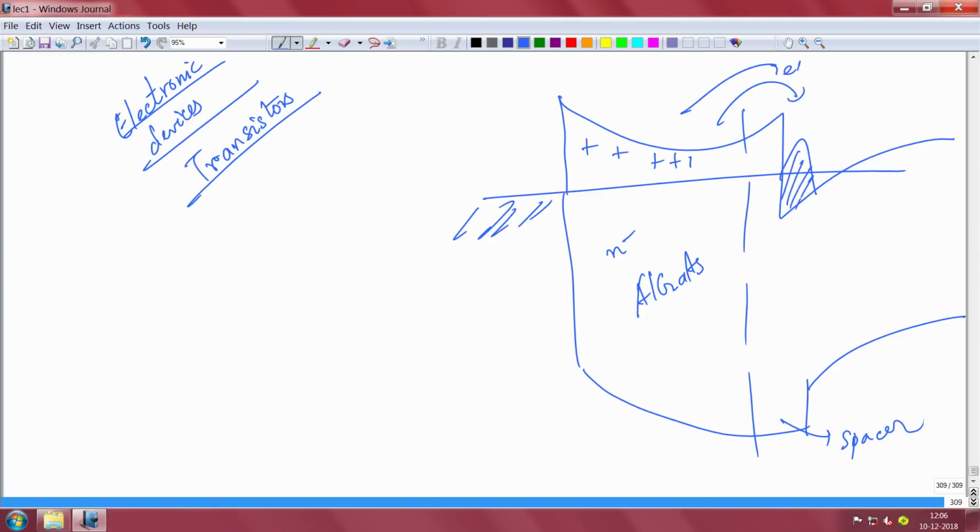Now the best thing about gallium nitride is you don't have to dope it because there is already polarization. The polarization that exists on gallium nitride and its sister compounds, aluminum nitride, AlGaN, InGaN, whatever, without any application of bias, without anything, is called spontaneous polarization, because it exists just like that.